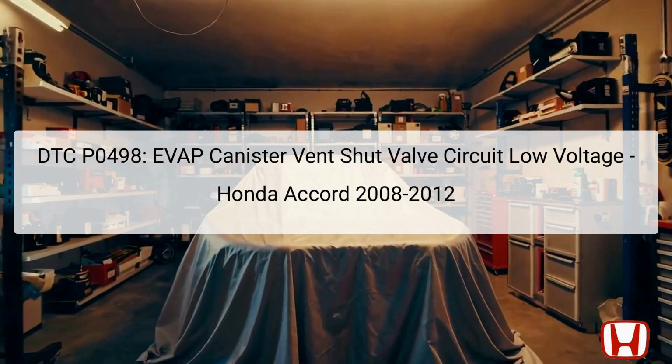The canister vent shut valve controls the flow of fuel vapors from the fuel tank into the canister for proper vapor management. A low voltage condition in this circuit can lead to ineffective operation of the system, causing increased emissions and potential failure of vehicle emissions tests. The sensor's location is typically near the fuel tank area, making it accessible for inspection and testing. Proper diagnostics will require specialized tools like the Honda Diagnostic System, HDS, to clear codes and check for faults.